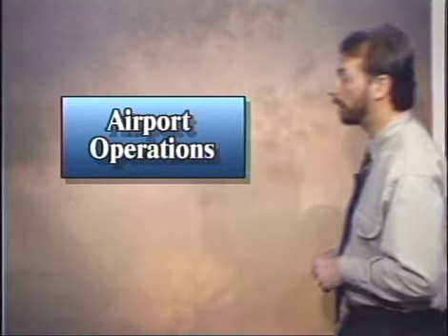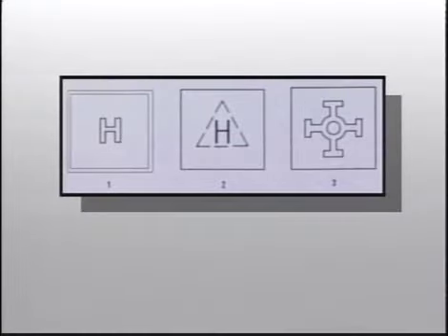Look at these 3 diagrams. Which diagram do you think illustrates what you'd most likely see? The recommended marking for a civil-use heliport is a square box with a capital H inside. Incidentally, the letter H in the box is oriented with the intended direction of approach. Be aware that heliport markings that look like diagram 2 are still in use, but a triangle with an H contained within it is obsolete and is slowly being phased out.